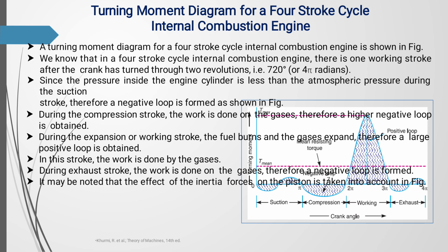The flywheel stores the energy in the form of kinetic energy. Then finally, the exhaust stroke. All of you know that clearly. The exhaust stroke expels all the unburned gases and remaining unburned fuel mixtures. Everything is exhausted through this stroke. This is the working of the four-stroke cycle engine.